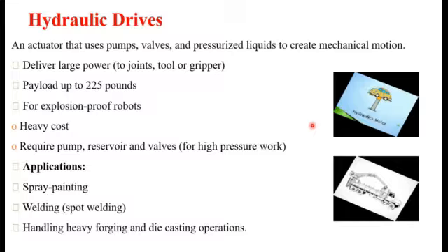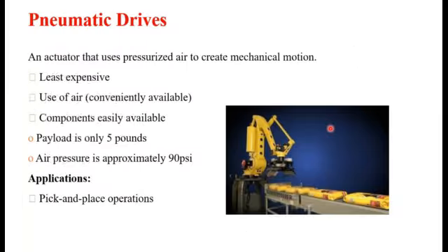Again, this type of drive has a higher cost. It requires a pump, reservoir and valves, and it is used for higher pressure work, so again it introduces some cost. Applications of this type of drive are spray painting, spot welding, handling heavy forging and die casting operations. This type of hydraulic drive robots are used there.